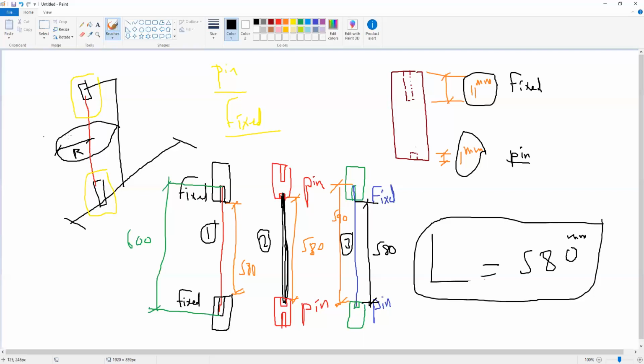So I return back to the test. For each case of them, what we will do is simulate the ends. The top end is pin, let's say, and the bottom is pin. So we will first add the first load. Then we measure the buckling, as the column will buckle a little bit. Then adding the second load, and the column will buckle more. Then you record the buckling, and so on, adding more load and more buckling until the final load, when the column will touch the ring. So when the column touches the ring, this means buckling.